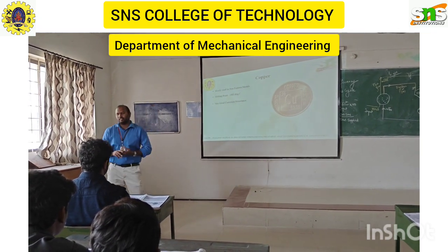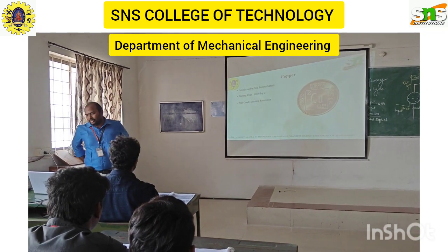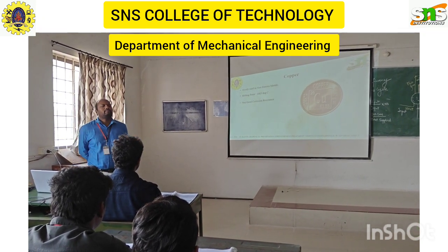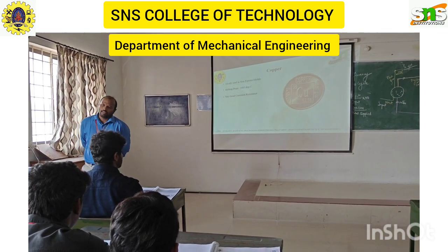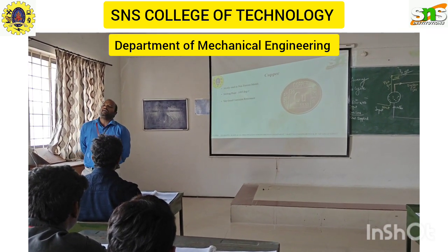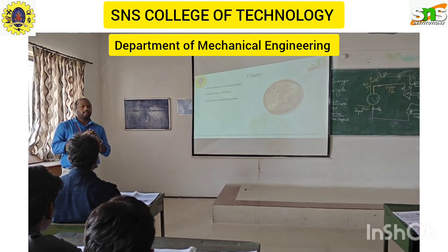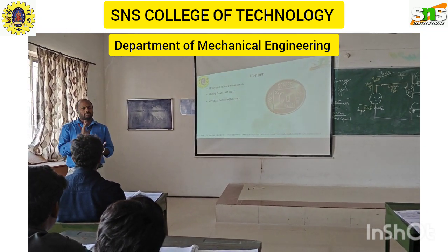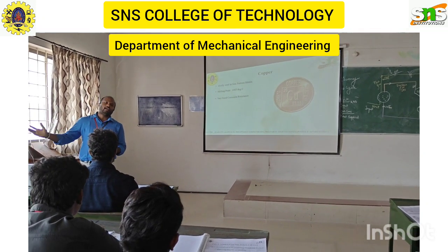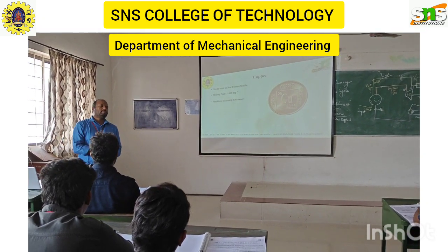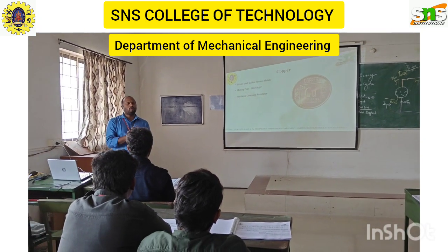The first one is copper, which has a melting point of 1080 degrees Celsius, and the major role of copper is that it has very good corrosion resistance. It's because copper, once it touches the normal atmosphere, forms a shield, something like copper oxide, so that the external air cannot touch the copper. Okay, it forms an outer shield like